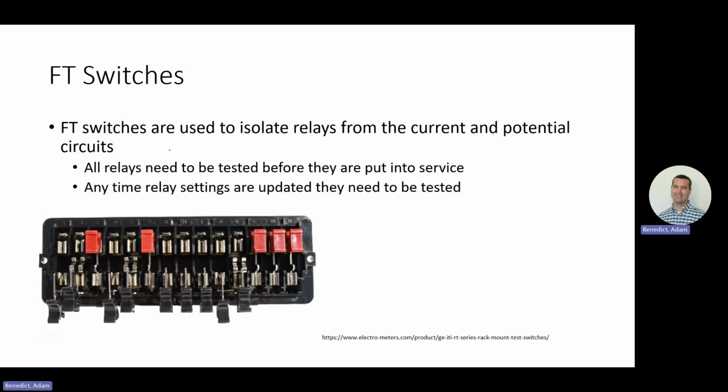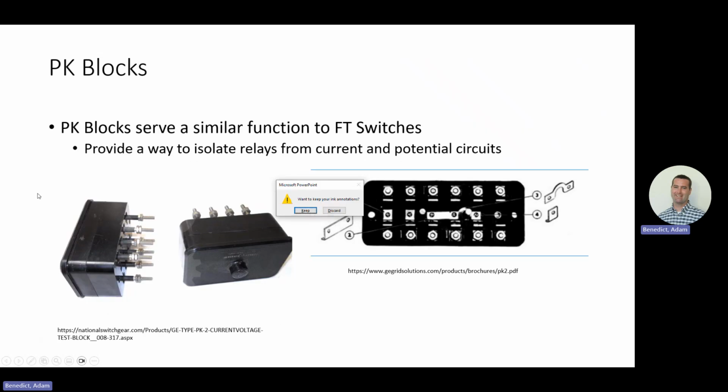FT switches. This is an important one. They are vital to what we're doing. They're used to isolate both relays, potentials, and also our DCs. All relays need to be tested before they're put into service, and these are very valuable for testing them. And actually, if you were to go to a website, let me see if I can pull up the website.